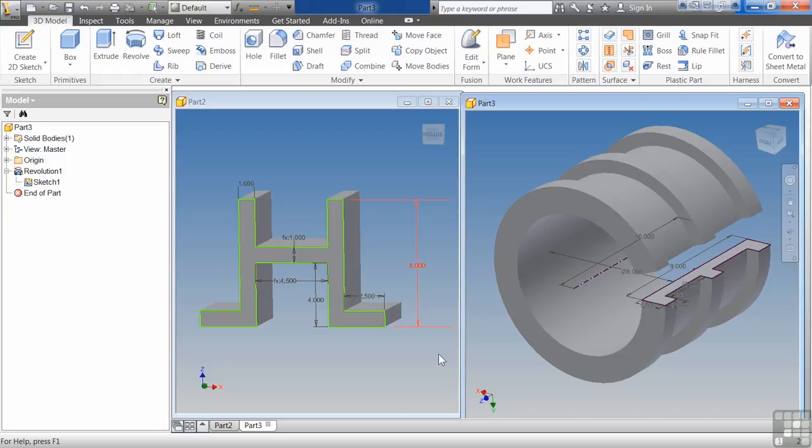In other words, if it doesn't do anything, Inventor's not going to let you do it. So you either extrude and add material or you extrude and remove material. For the base feature, it's always going to be add material. There's nothing to remove material from, so you have to have a base or a starting point. You have to have some kind of mass there to remove from.